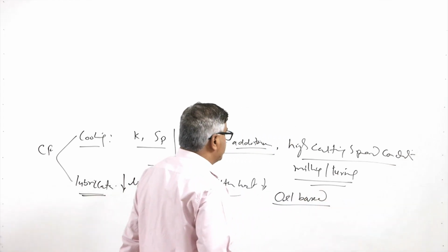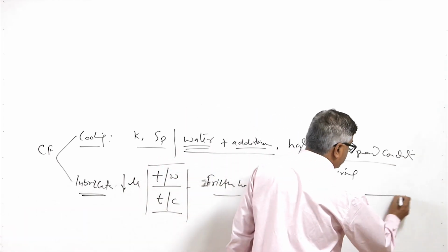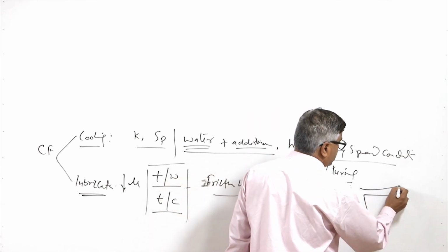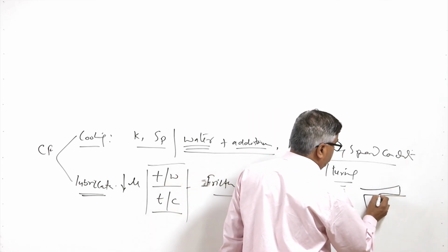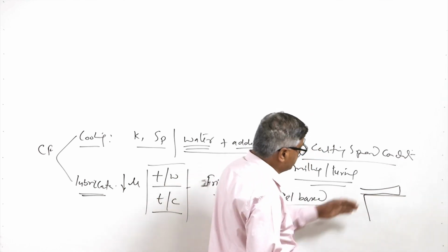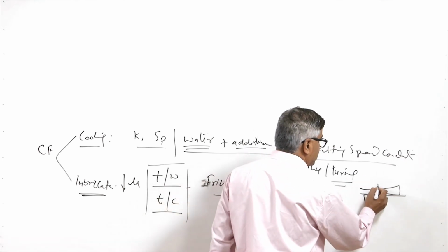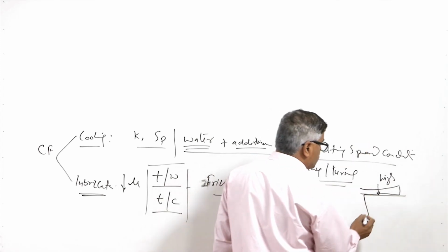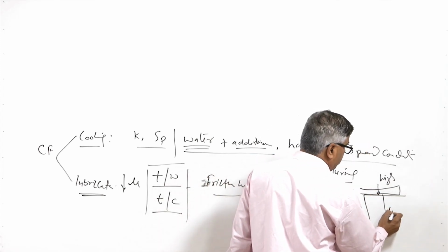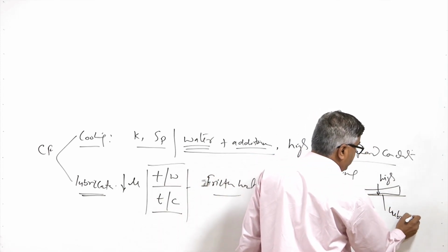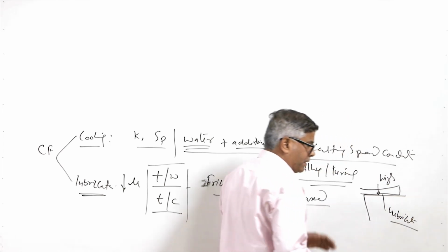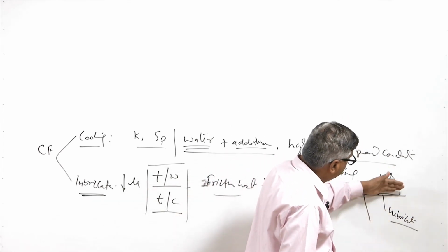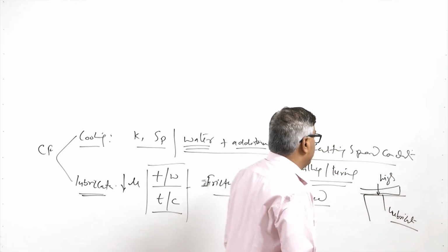But since the stresses, or the pressure, present during the flow of the chips over the face of the tool are high enough, any lubricant, if applied, can be made unstable, so that direct metal to metal contact between the chip and the tool is present.